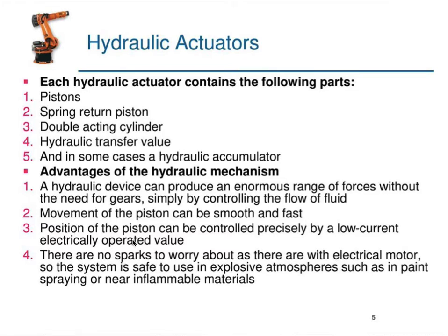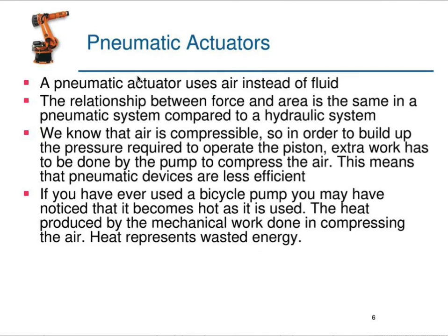Third, the position of the piston can be controlled precisely by a low current electrically operated valve. And last, there are no sparks to worry about as there are with an electrical motor, so the system is safe to use in explosive atmospheres such as in paint spraying or near inflammable materials, isn't it? Now come to the pneumatic actuators.